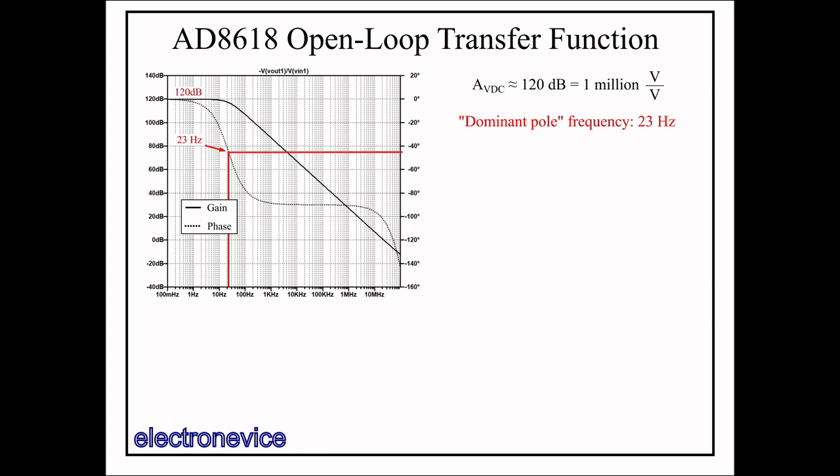But for frequencies beyond the first pole's corner frequency, the loop gain is essentially the same as with the op-amp unloaded. Due to the difficulty in measuring high gain and low frequency, most op-amp datasheets won't show very low frequencies because when the gain is very high, it doesn't really matter what the gain specifically is, as the ideal op-amp equations will be very accurate in that regime. The DC gain is a useful parameter to measure, but after that it's not usually important until the gain gets to around 60 dB. So, after the first pole, there's a very large amount of frequency before the next pole comes into play, as we can see by the phase flattening out to -90 degrees, and gain decreasing steadily by 20 dB per decade of frequency, as expected from a single pole.